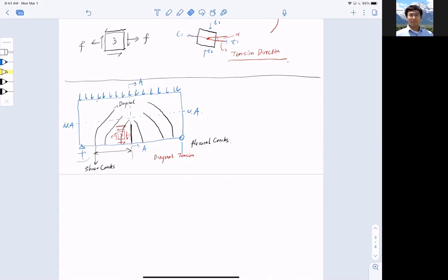And I even don't care about the names, diagonal tension, anymore, although you should really care about it because we'll ask you about it in the exam. And the support is right here still. I want the supports to show. And then I just have the cracks. So clean up this, and I only have the cracks like this. Let me make this one symmetric. All right. And let's say as it gets a little bit more in the middle, it gets flatter. So just to exaggerate, let me draw it this way, more flat. And I'm going to design my reinforcement accordingly.